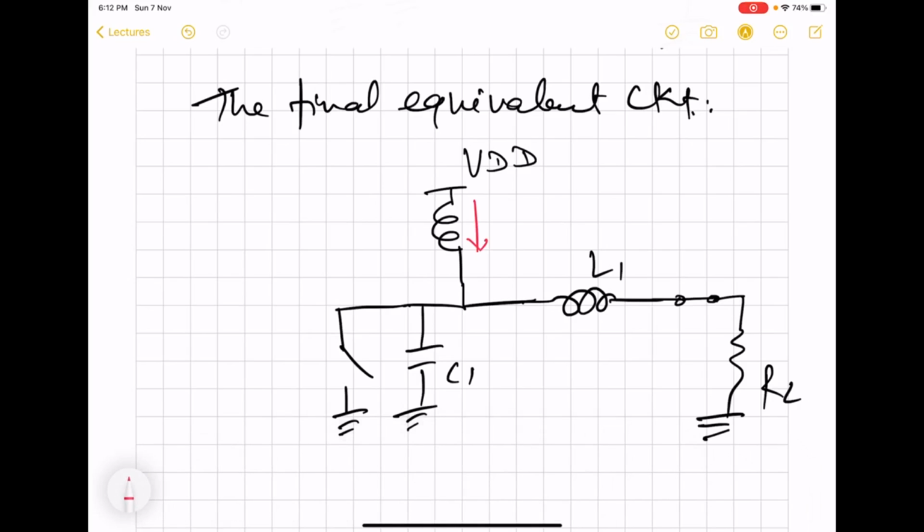So first is going to be well known DC current, which will be flowing through RFC, and then of course current I1, which will be of sinusoidal nature, and then these two currents, they will combine here to produce total current I. And since switch will be closed for one half of the input and open for the other half, so this current will actually get divided into these two parts through the switch, which we will be calling IS, and through this capacitor IC1.